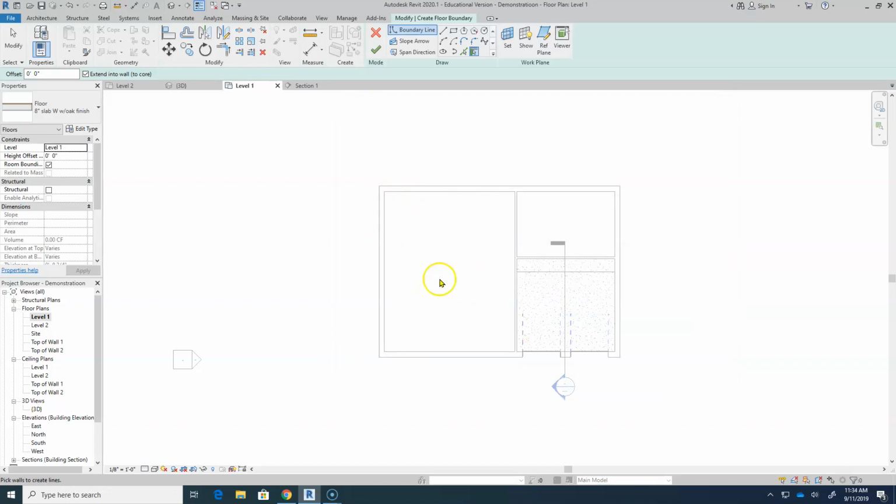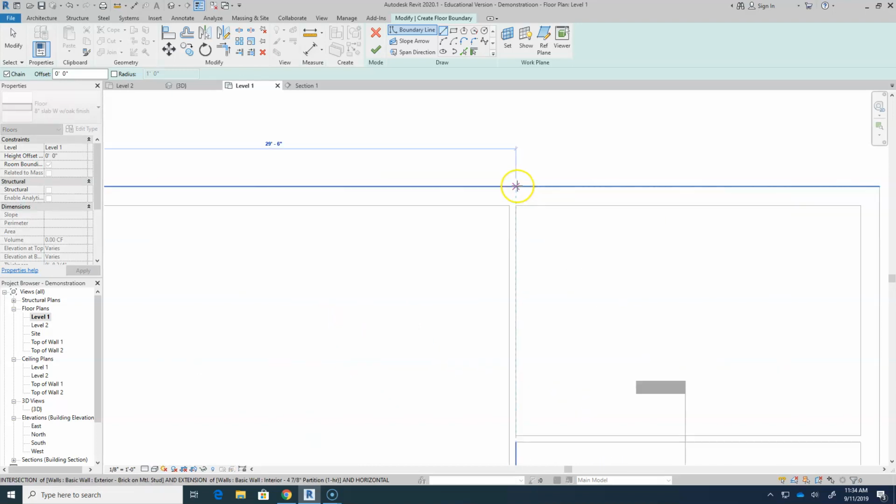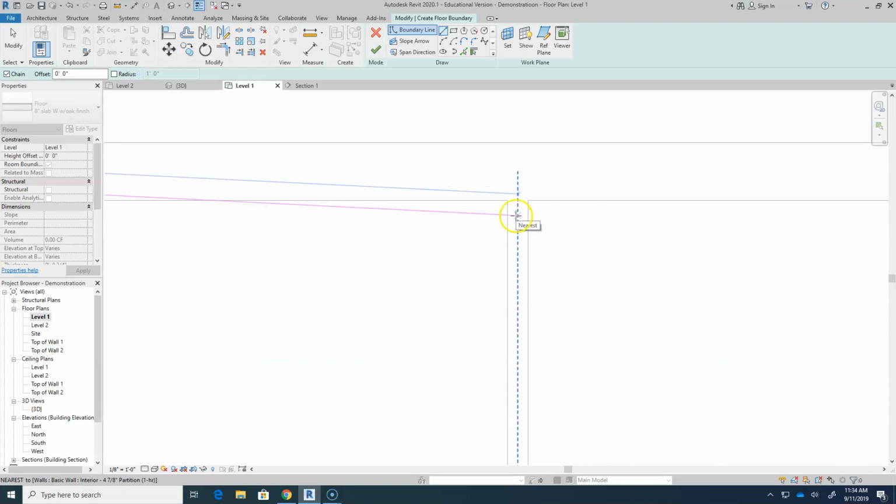So now you can pick walls if you want to, or you can just draw it out. It's probably, maybe a little better. I mean, it depends on you, really. Now, of course, it's important here to remember that these floors, the finish of the floor, is going to extend under the wall up into the core. Okay, so there's no real selection here that will allow me to select like an exterior core face or anything. So I'm just going to kind of guess.